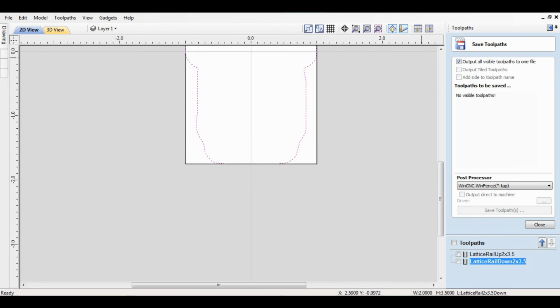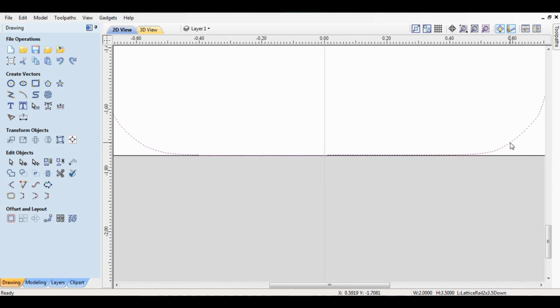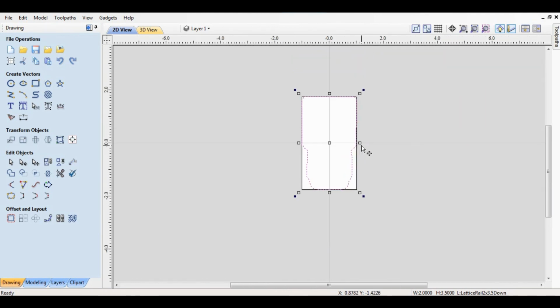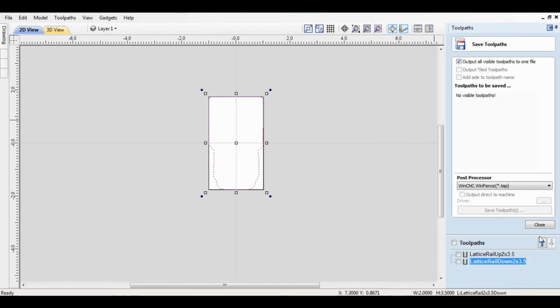I'm going to go back over to the other side here to my editing tools, and with this selected, I'm going to go back over to that join a closed vector with a straight line, select that, and now if we come in, you can see that we have a solid shape here, no tongue coming up inside to mess things up, and I believe that everything would work better.